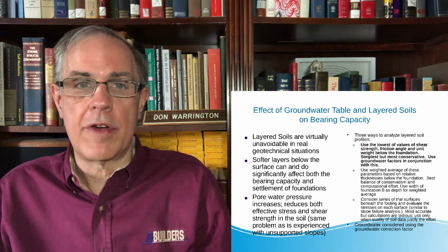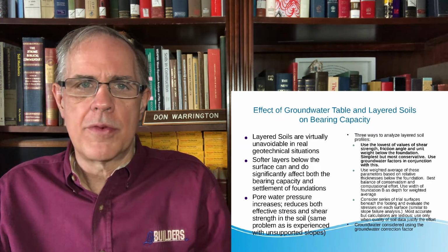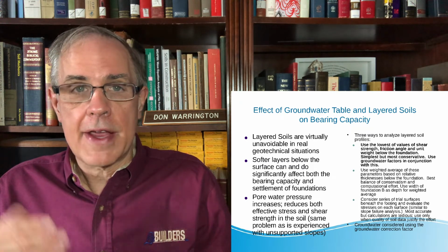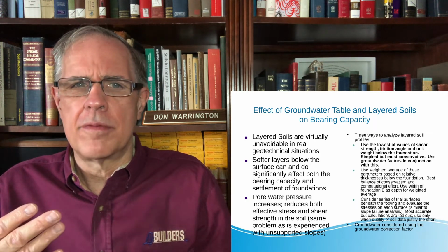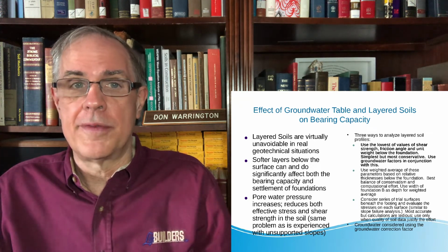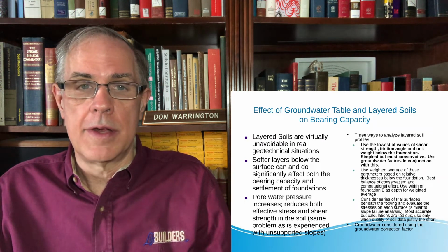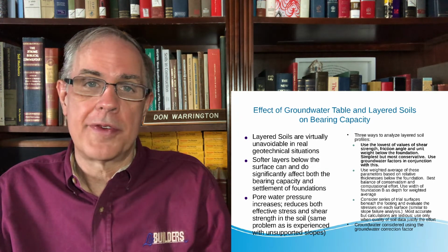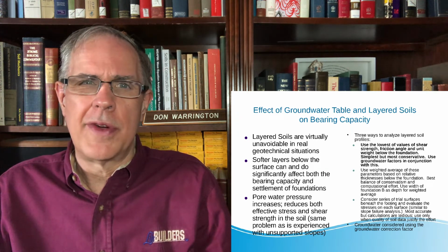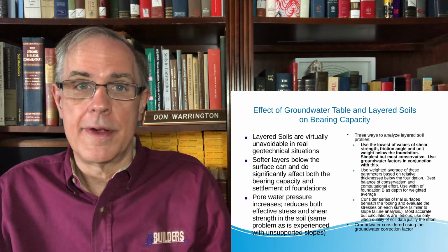Use a weighted average. Weighted average is what I taught for a long time. The only thing that trips up weighted average, other than being complicated, is that if you've got a very, very soft layer, the very soft layer will drive the whole thing, and you'll have problems. And of course you could go through trial surfaces. I wouldn't recommend that. If you've got something that complicated, you probably need to do finite element analysis.